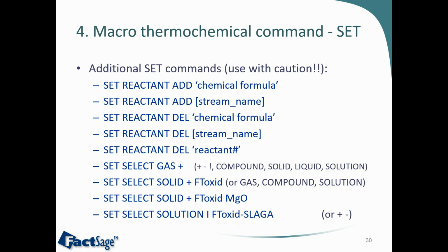One disadvantage of using set select here is that it does not follow the default phase selection defined in the equilib module. For instance, the default excluded species marked with the X inside the equilib module from the database selection in the compounds, and the default I or J option for the solutions that are applied automatically in the equilib module are not applied when using set select.